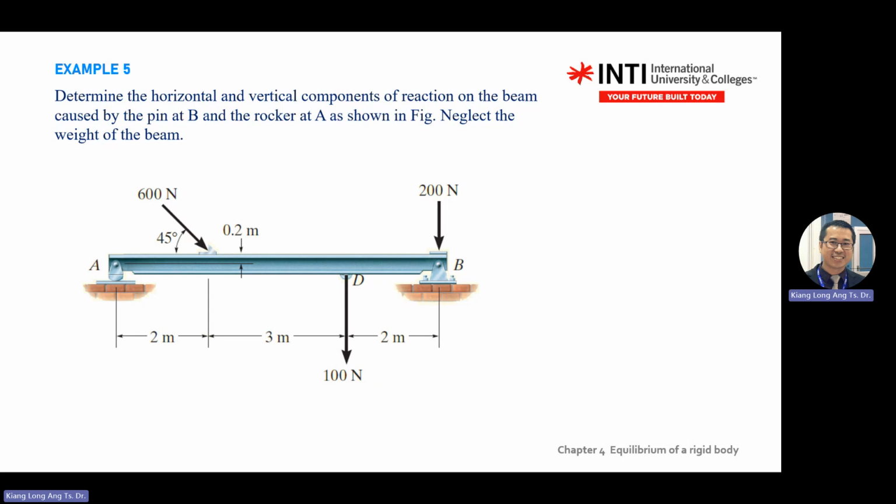But because this one is calculation, go up positive, go right positive. So AY go down, remember put negative there. This one as a side calculation. No negative in the free body diagram. This one is your side calculation. X is go to the right, so positive.